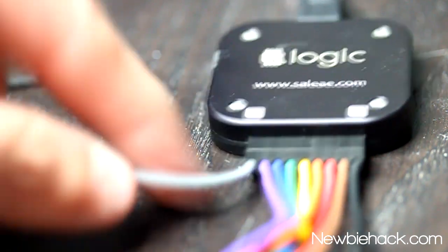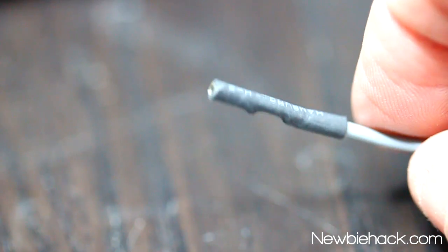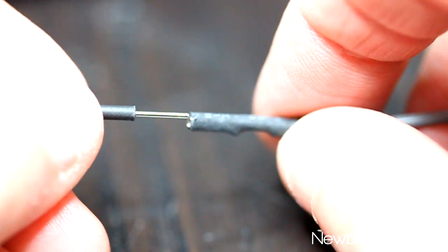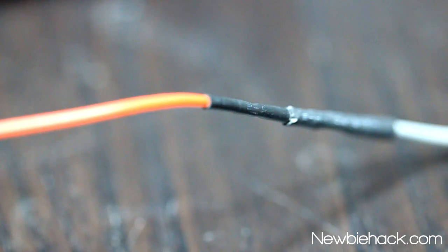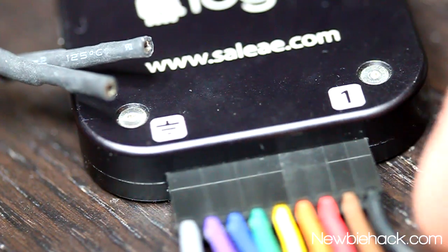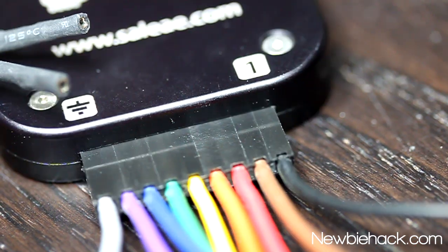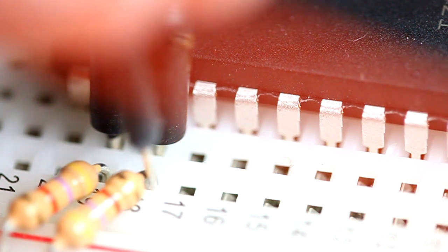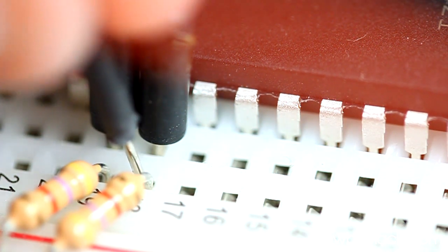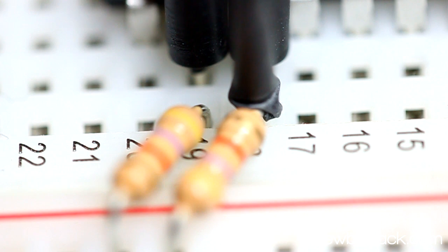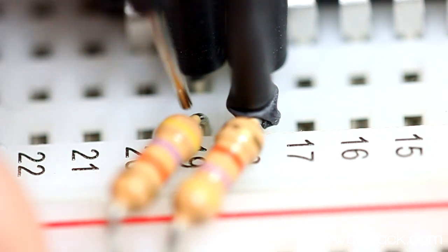The gray wire will go to the ground. Since the lead doesn't have a male header on it, I'm going to just connect a jumper to it, and I'll connect that one to ground. The black lead connects to the SDA. Not much space, but I'm going to use the same place where the resistor is. And now we'll use the brown for the SCL. I'm going to do the same thing, plug it right where the resistor lead is.